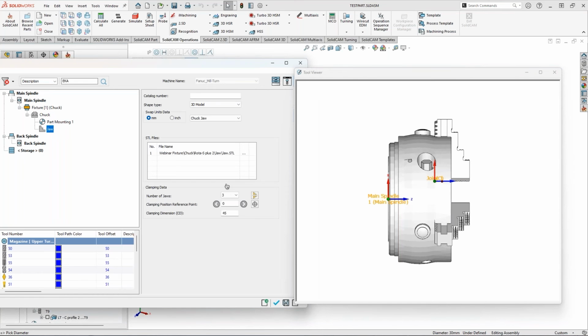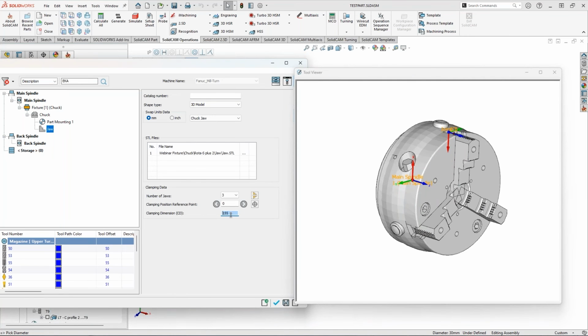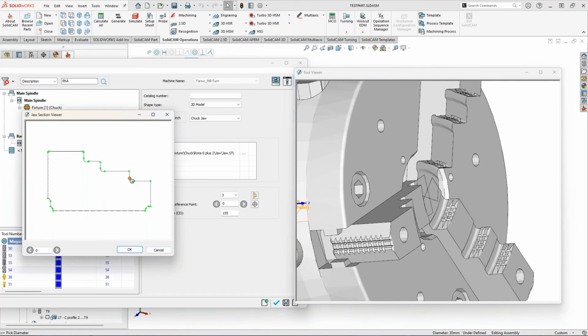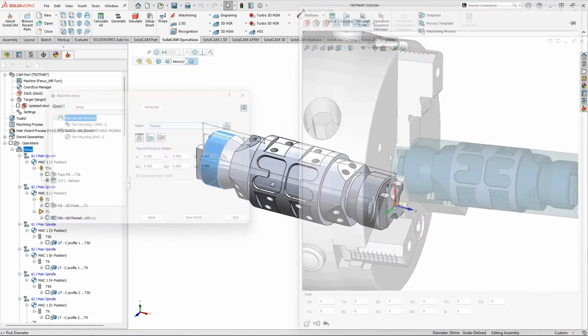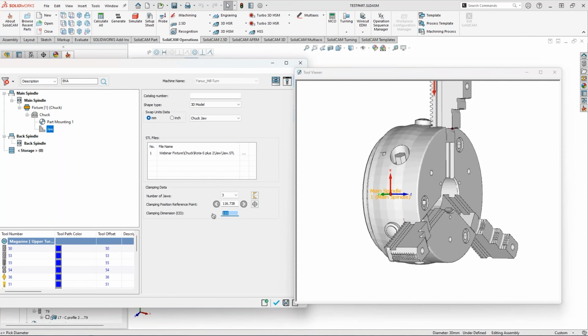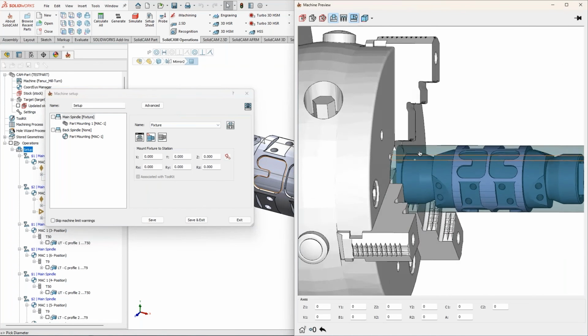I'm going to open the toolkit again. In this example, I'm going to switch these positions and try to clamp it over here. So I'll change my reference position to, I think, this is the one. So it is over here, you can see. I'll just accept it. I'll click OK and accept it. One thing I forgot is to increase the open position. So let's say 45 was before, so we can keep it on 45. That will be fine.